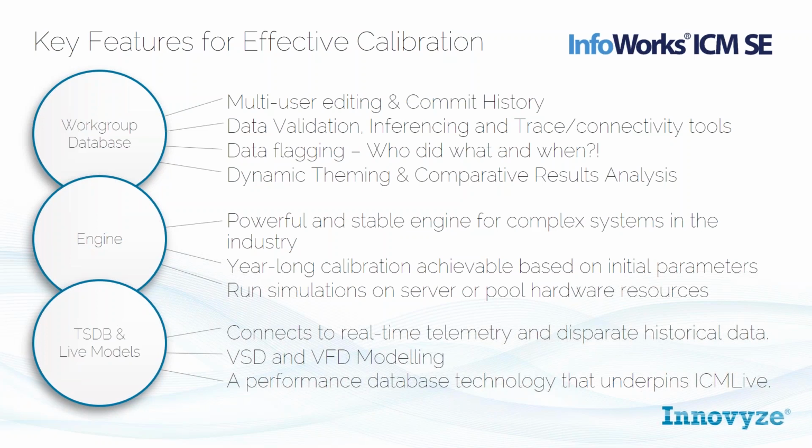So a tip I've got is when you're doing your initial runs, you turn on the run diagnostics in the model and look at the time step halvings. You can also see where you're getting a lot of time step halvings in the run dialog boxes. So really have a look at that and focus on where those are occurring and try and resolve those. Anything you can do at that stage to decrease your run time is going to save a huge amount of time as you go through the calibration process.